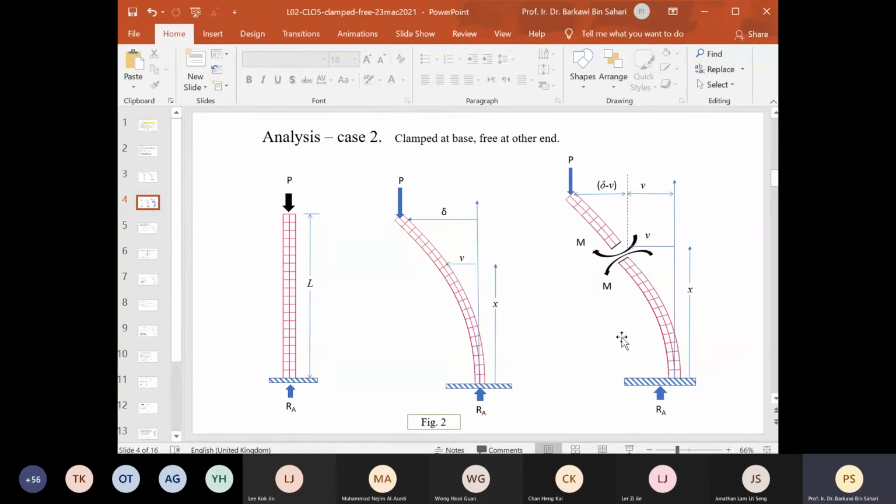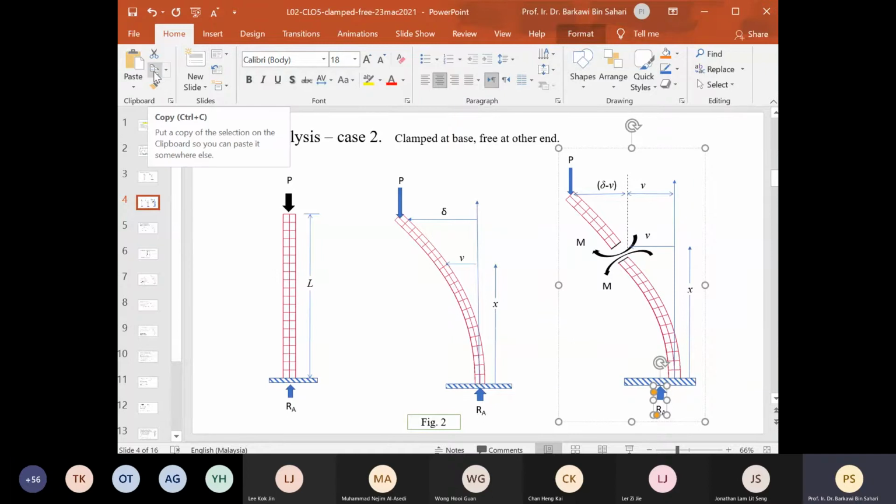So the rest of the forces are still intact. I think there is one more force, P, at the cut, at the place where it is being cut, to maintain equilibrium. So I put that in for completion of the diagram. It doesn't affect the moment equilibrium because P is located at 0 distance from the place of the cut, internal. So I just put there still P.